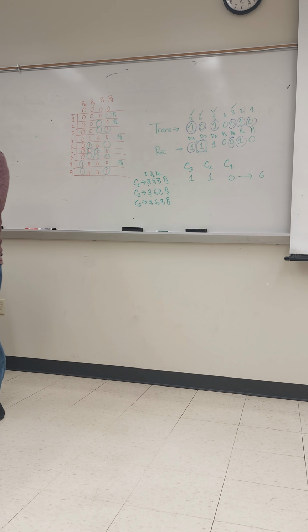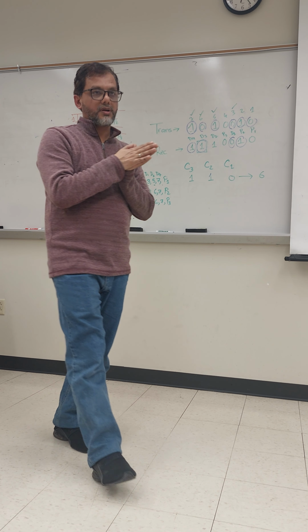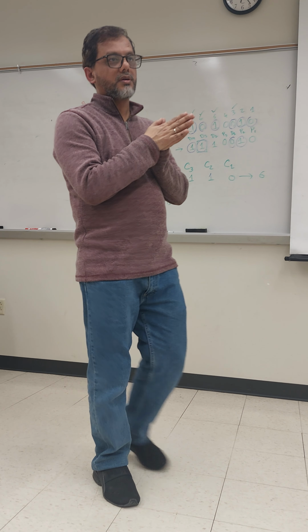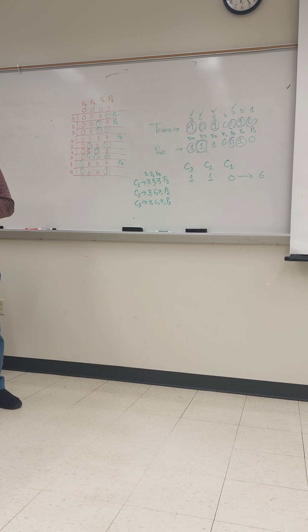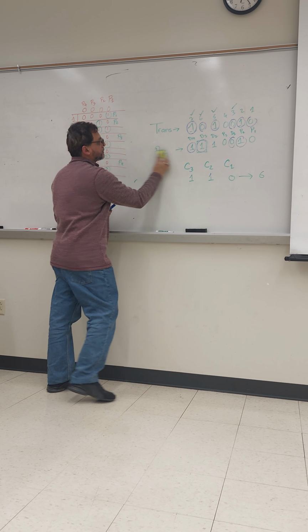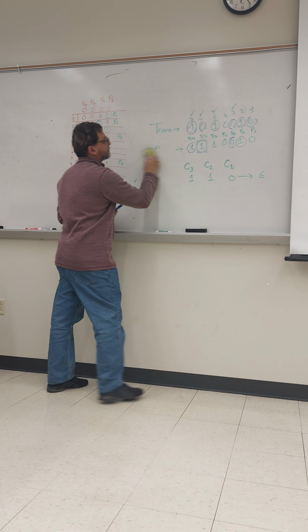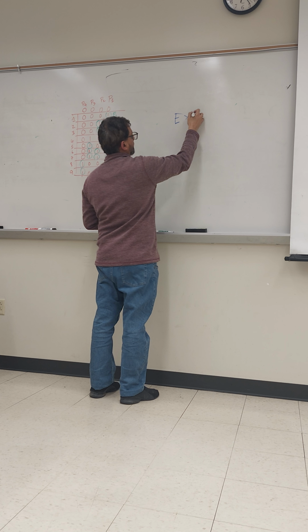But there is a drawback or limitation: it can detect and correct only one bit error. If there is more than a one bit error and you want to find it, we need to add another bit. It is known as extended Hamming code. If you go to the next slide, slide number 29, you can see the extended Hamming code.